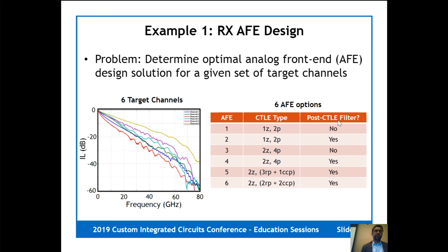Right. So for the first question, I'd say the transition to PAM4 was primarily driven by the channel bandwidth limitations. In many of the backplane channels, there is pretty steep frequency roll-off going from 14 gigahertz to 28 gigahertz. But those are not present in the very short channels, which is why NRZ is still applicable there. So the technology itself allowed us to push the baud rate from 28 to 56.